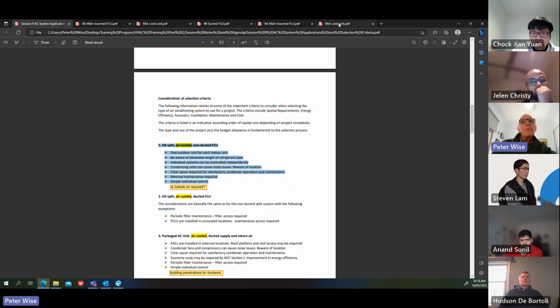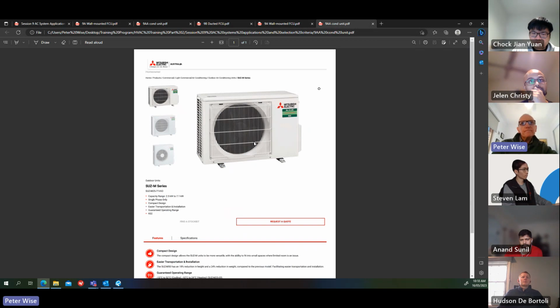So I'll just have a look at that condensing unit again. So air has to come in to the condenser and be discharged from the condenser at the front. And these come in various sizes and shapes. They might have 2 fans, so they're a bit taller, a bit wider. But you need to have a look at the manufacturer's recommendations and make sure that you've got intake and outlet space around them. Otherwise, they won't work properly.